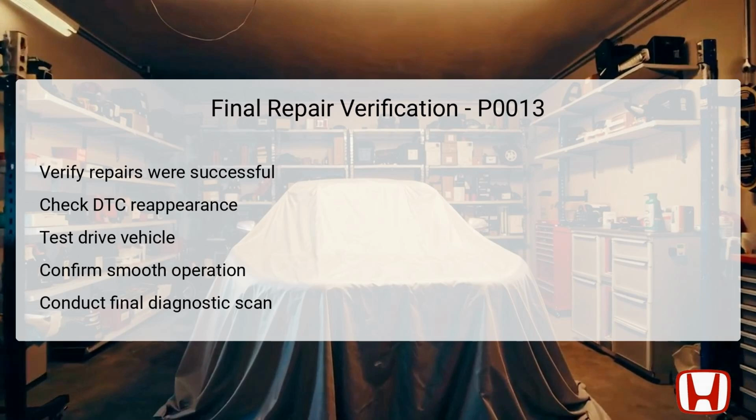During this test drive, pay particular attention to the engine's response when accelerating and at idle, confirming that there are no irregular symptoms present. Lastly, a final diagnostic scan will help confirm that the vehicle systems are functioning correctly and that no new fault codes have emerged, ensuring the Accord is road-ready.